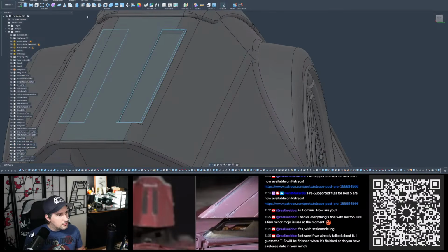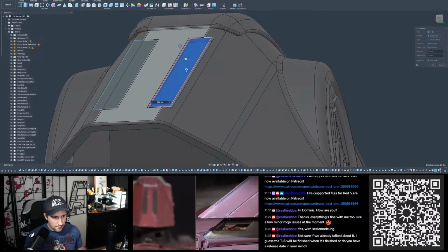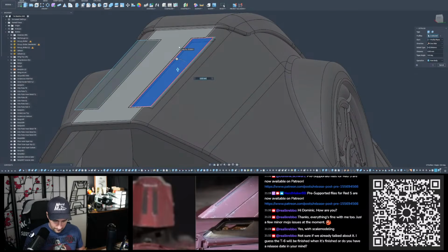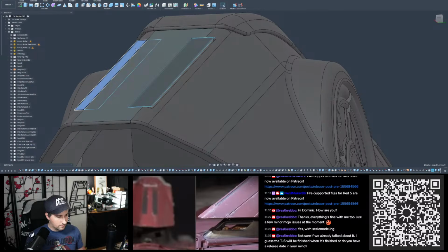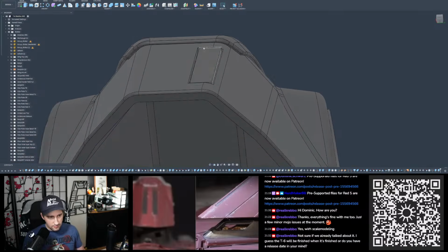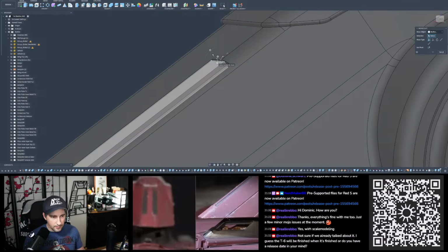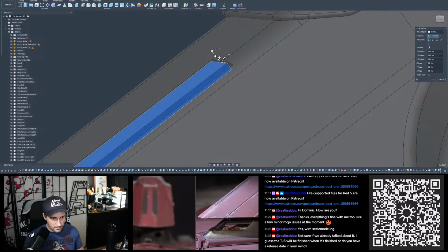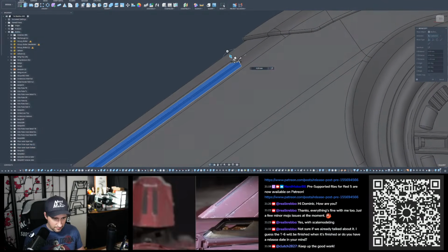Okay, now I can extrude the inside. Guess I can make this the same. Let's make this a new body. Hide the sketch for now, and then let's rotate this a little bit and push it inwards for like 2/10, maybe 3.